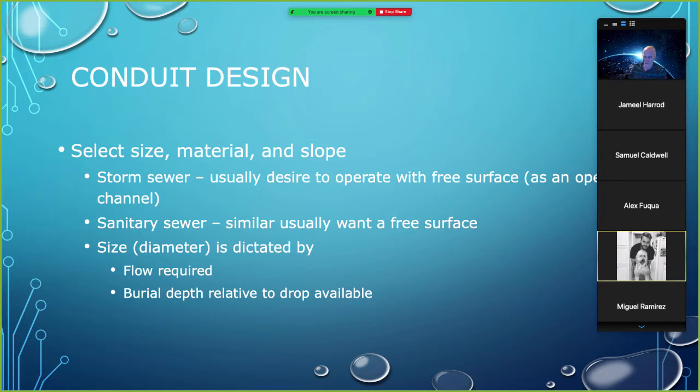It's actually a really good material for stormwater and for sanitary, but it requires a level of placement skill that's not economical to find anymore. So it's becoming less and less used in new installations. A clay pipe is likely to be around for quite a while to replace existing clay pipes as they fail.